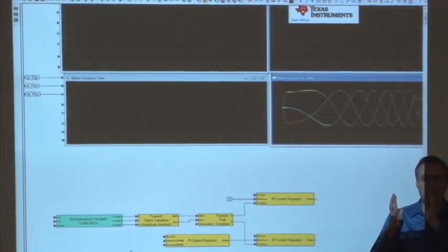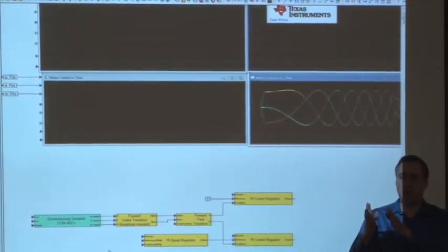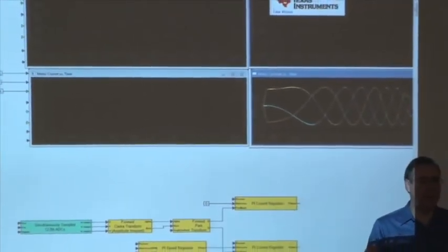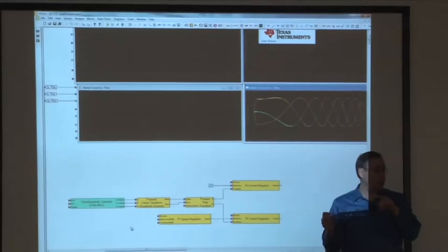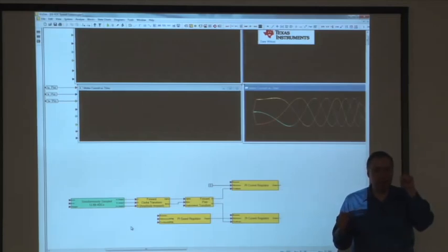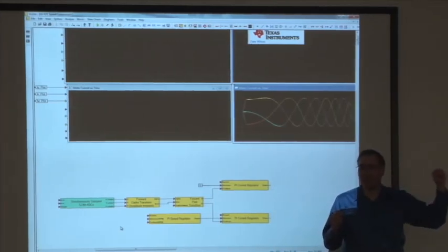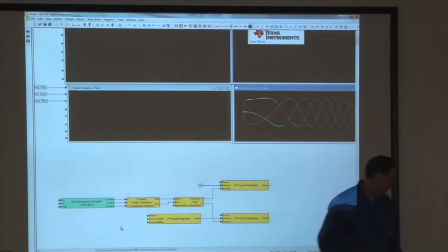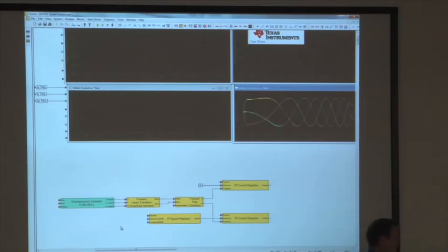We want to do these at a certain time in the PWM waveform because that's where we capture the value to be just right. In other words, the current waveform, if it's under PWM control, remember it's rippling, right? It's got ripple on it. If I capture it right in the center of that ripple, that's where I get the average value of the current. So when we put the PWM module down, we're going to create an execute signal, which we're going to feed back to all these other blocks to say, okay, run now. All right, so we'll leave that blank for now.